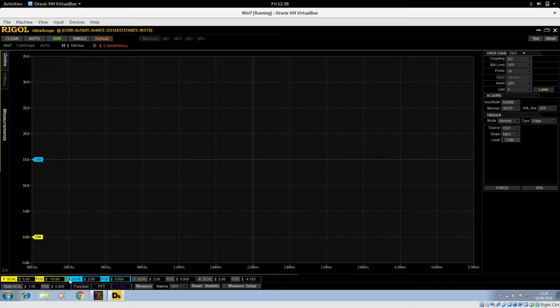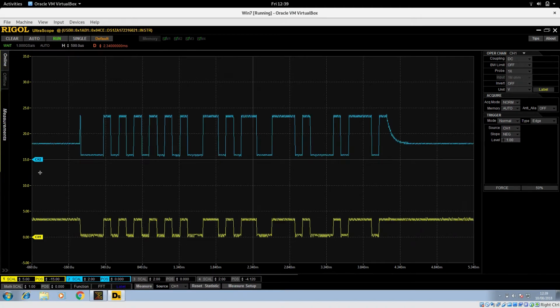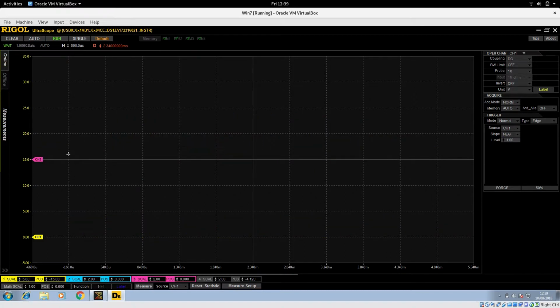Now A, if we look at A, you can see that when this is a logical 0, sorry, it's a high voltage. Before we grab the receiver, look, the RS485 transceiver's in the idle mode there. It's listening for something. But we then grab the transmit, say we're going to transmit, and it then drives the line high on A because we're transmitting an idle, which is logic 0, which is a high voltage. And that's the two combined. Wait for it to trigger again.